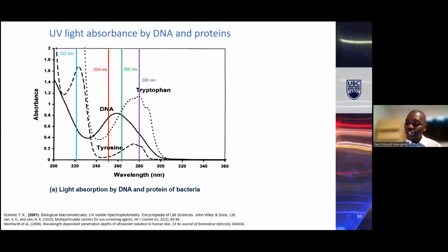So for the inactivation of MS2, if you are able to reach a certain percentage, let us say 99.99, you have killed the MS2. That means E. coli, you can destroy all of it. And remember, MS2 is used because it is highly resistant to UV. That is why it is used in the validation of the UV system. Therefore, when you take the UV system on the ground, you have tested it with this highly resistant microorganism before you take it on the ground.